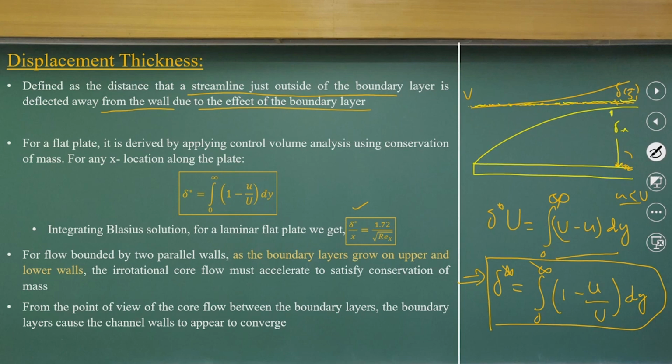So, that means we are getting another thickness, which is the displacement thickness, delta star here, which is a function of the same quantities. Earlier the coefficient was 5, now it is close to 1/3 of that, divided by the square root of the Reynolds number at x. As we know this velocity distribution, we can get this value just by doing these integrations. The equation format will be the same, the trend will be the same. So, this is the displacement thickness.